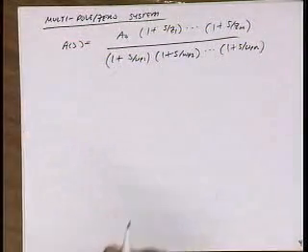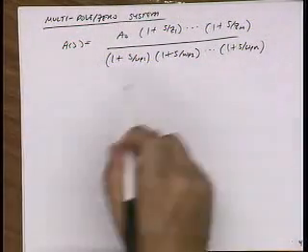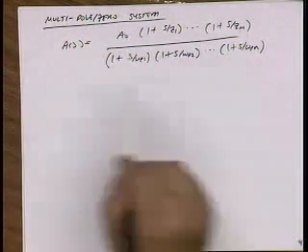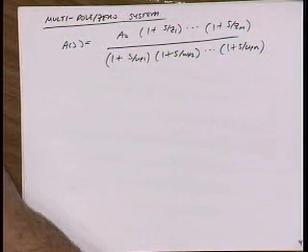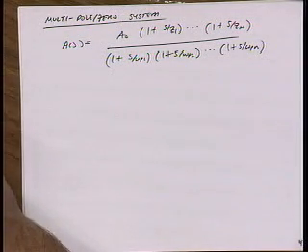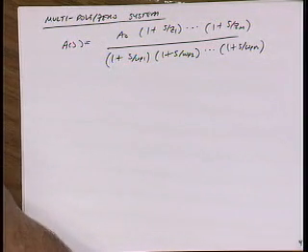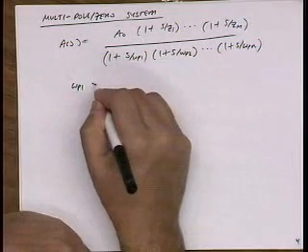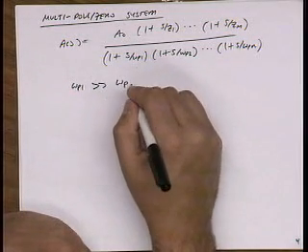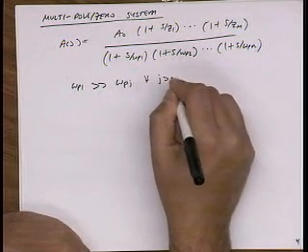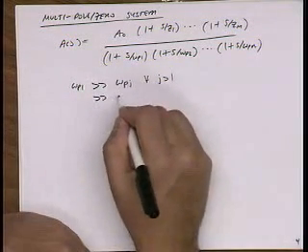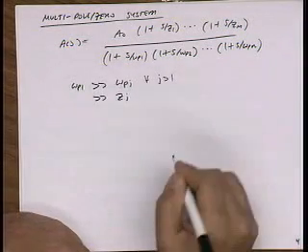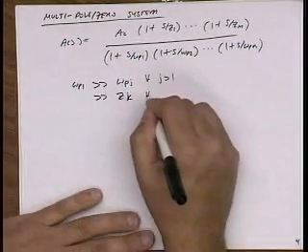Okay? But, of course, we know that this system won't work unless it has a dominant pole, right? If we take this amplifier with all these poles and zeros and put it in a feedback loop, it's going to oscillate, right? Because there'll be more than 180 degrees phase shift at unity gain frequency. So, in other words, this system will only work if omega P1 is much greater than omega Pj, and also the same applies to omega, let's say, Zj. Well, let's call this K, because that's for all K.